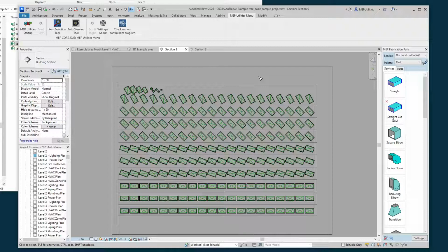The other great thing about this, too, is you don't have to be really well trained in this situation. You don't have to train someone to place sleeves on these pipes and how to place them and how to size them and all of that. You don't need to know that. You just have the program, select the items, you push the button, and anyone, even people who don't know how to use Revit, can sleeve an 11-story building in 20 seconds. So that's a pretty powerful tool.